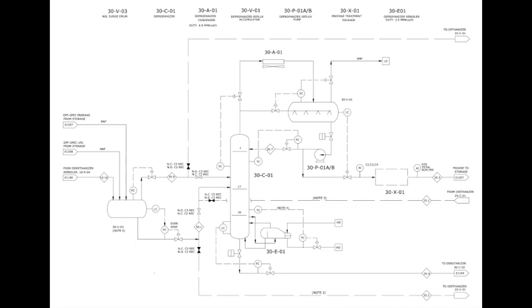Let's go to the bottom. Here you will see a level controller on the left that controls the level of the liquid in the lower section of the column by controlling the flow rate of the bottom product. Here also there is a cascade between a flow controller and the level controller to manipulate the bottom product of the column.